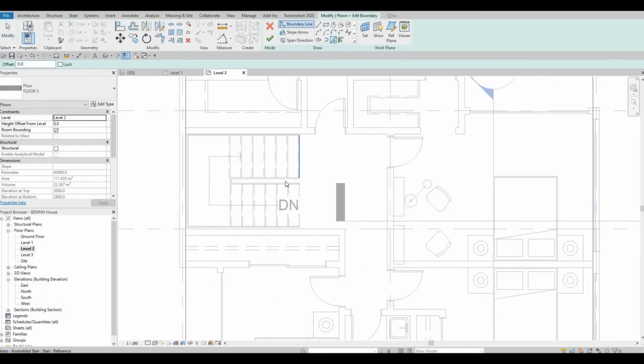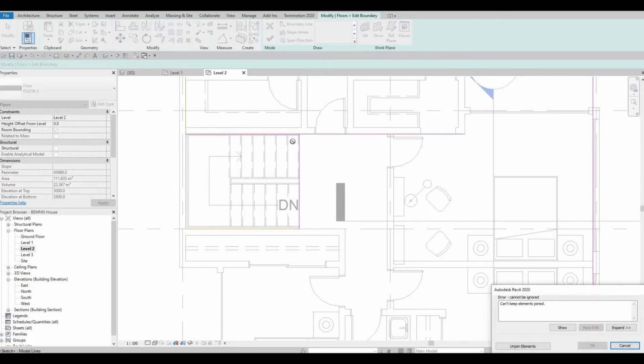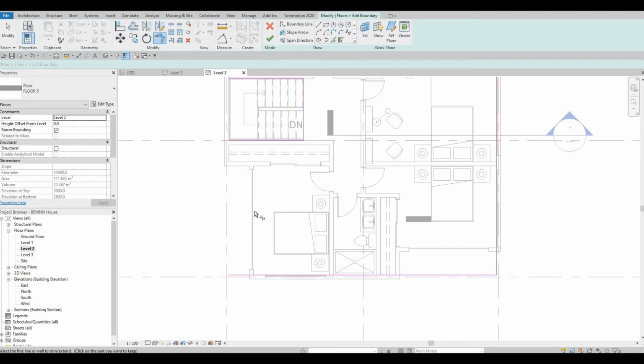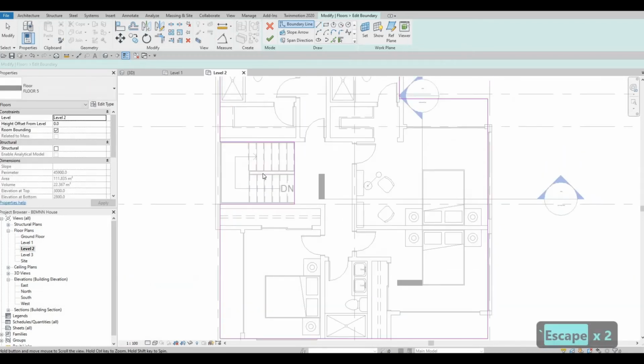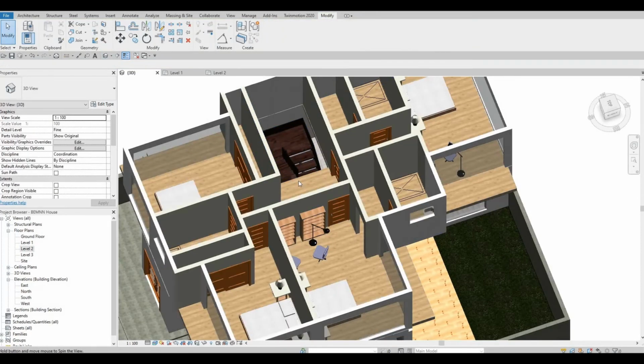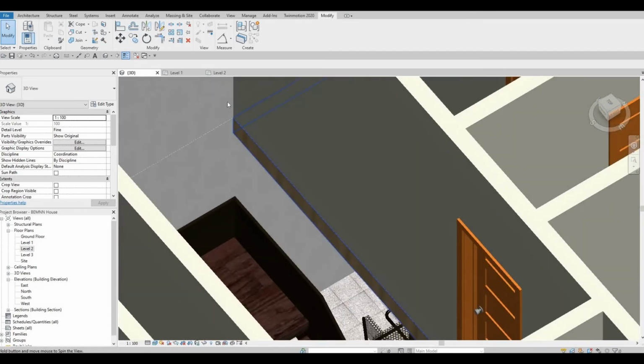We just need to select here, select this side, and then this side, and then TR, trim and extend right here, trim and extend right here, and join, TR right here, and then now we could just add a line right here. And then after that, click finish, and we could see below there. So that's good.